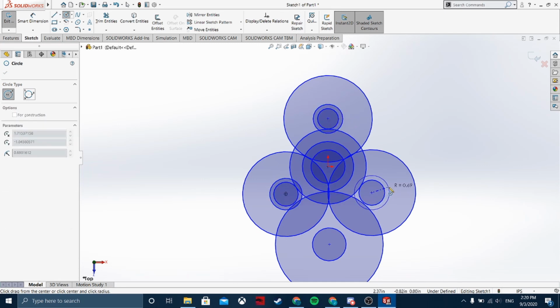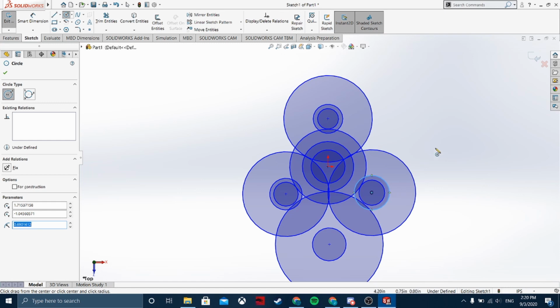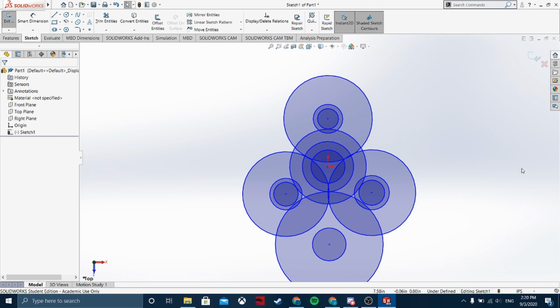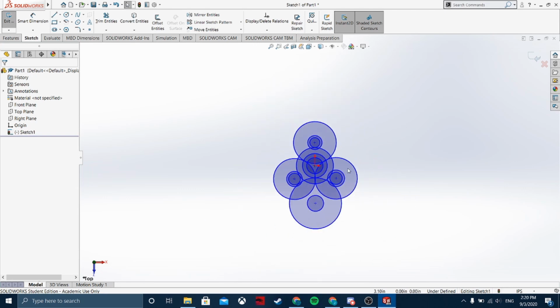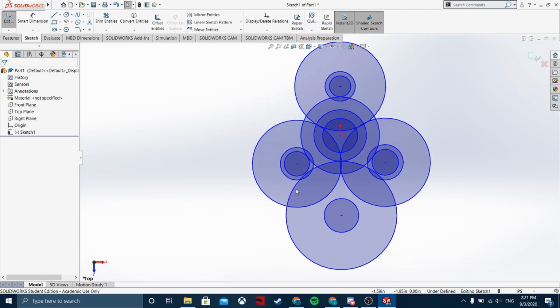The reason we need pinion holes is that since the motor is going to be below the plate and the pinions are going to be on top, there has to be some way those two connect. So there has to be a hole in between so that the pinions can fit in. Okay, I think that's good enough for now, because there's extra stuff that we have to add. But for now, this looks pretty messy, so I'm just going to define all this first.